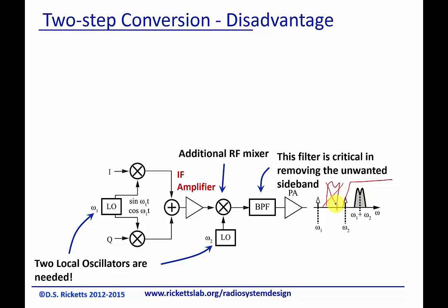A lot of cell phones now use surface acoustic wave filters, SAW. Basically, they take an electrical signal and launch it on a piezoelectric substrate in a way that it only transmits a very narrow band of frequencies. The reason we do this is these filters have extremely low insertion loss and extremely sharp filtering, so it's worth it to go into a specific technology just for these specialized filters.